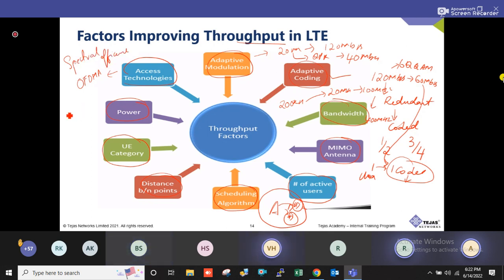when compared to whatever we have in TDMA or even in CDMA. Okay, so spectral efficiency, just to give you an idea, how do you calculate it? It's very simple. Spectral efficiency has the unit bits per second per hertz. That means how much data rate you are getting. Let's say I get 120 Mbps using 64 QAM modulation, what is the given bandwidth?